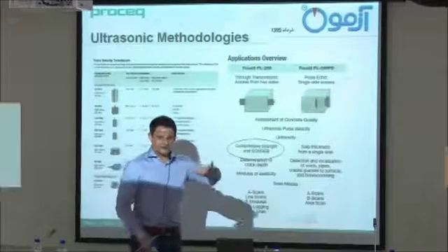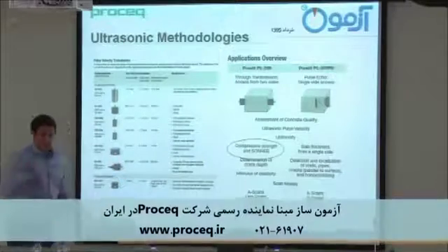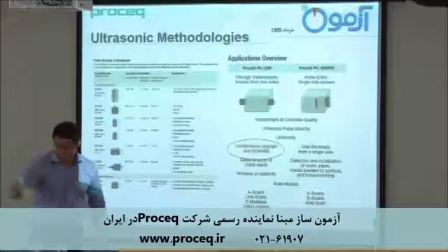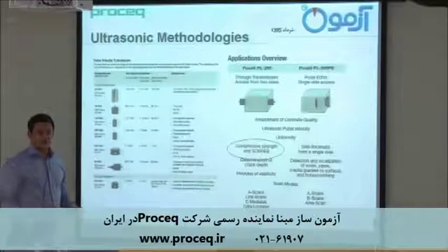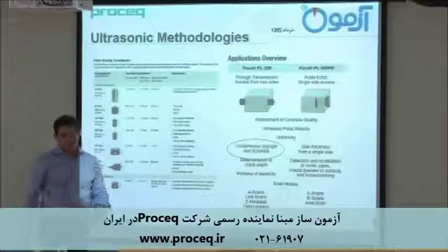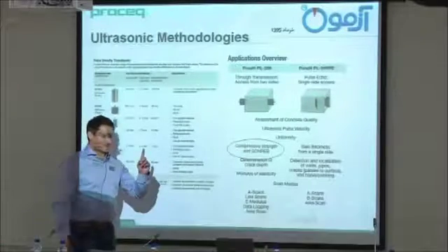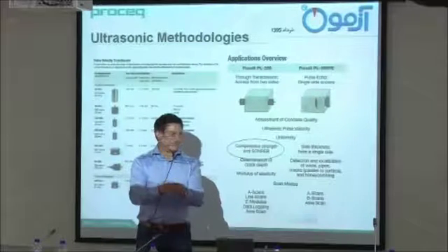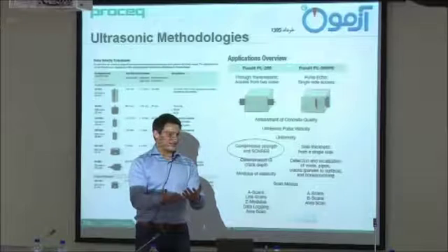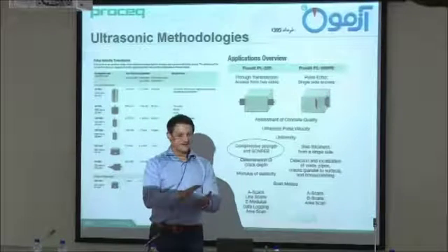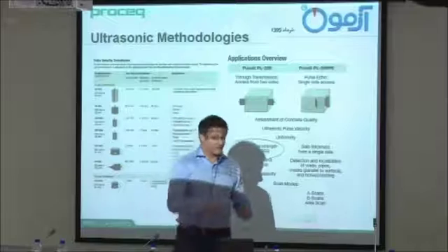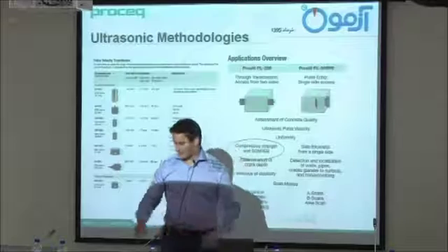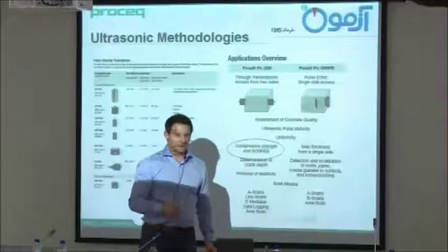Sometimes you have a very rough surface. Couplant is more or less, I brought it with me, just liquid. When you have a rough surface on the streets, it's also not that nice. What you can use, I'm not too sure what it is in English, you know when kids play with plastiline, green, yellow, it's really good to use. You push it on the rough surface and then use this, and if it is not enough you can use this or just a bit of honey, just some liquid.